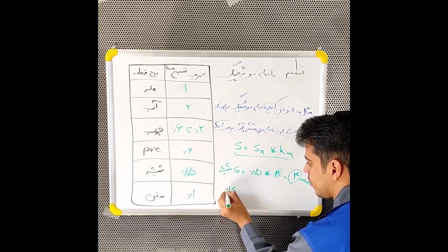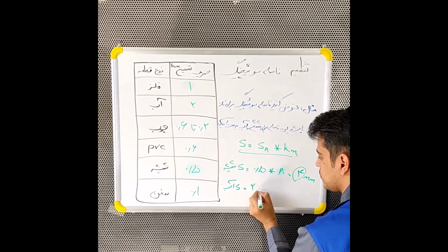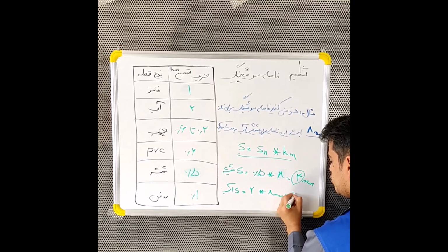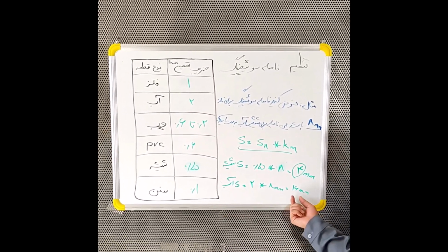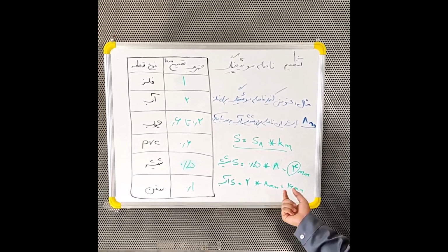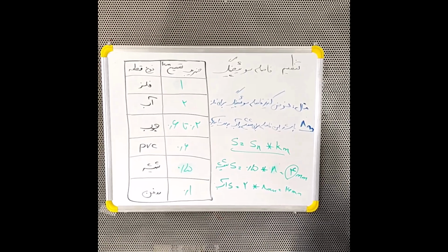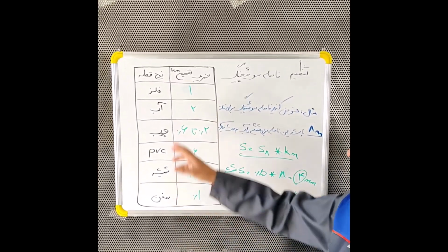The detection distance for water is equal to, so we multiply the value of 2 by 8 millimeters. So the maximum distance for water detection is 16 millimeters. All these materials can be detected by this sensor and the distances are different.